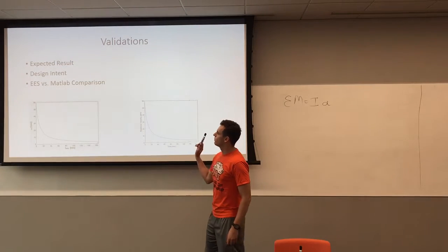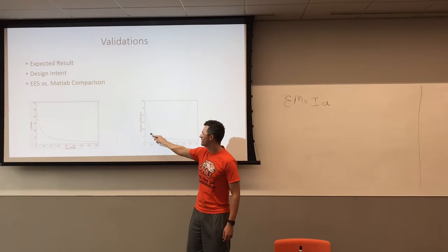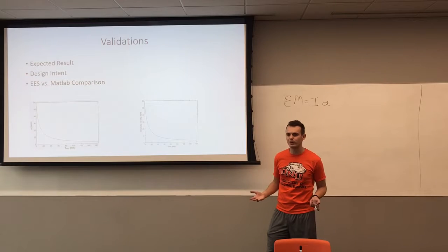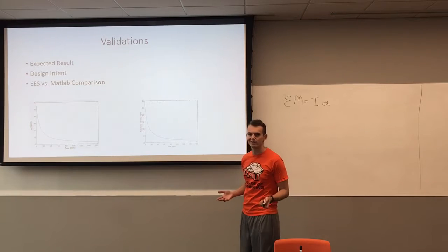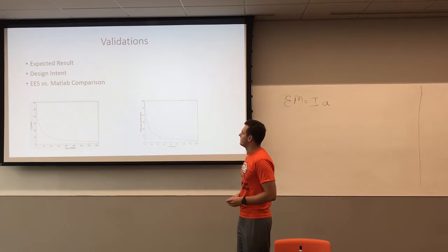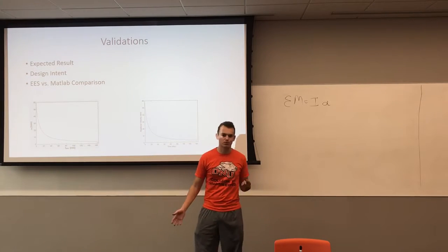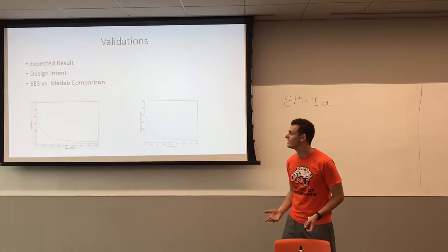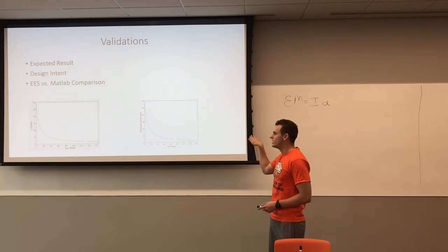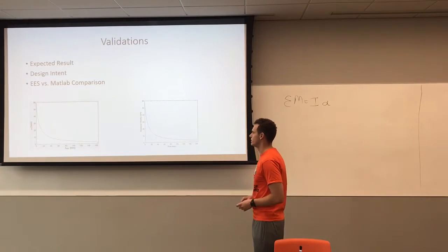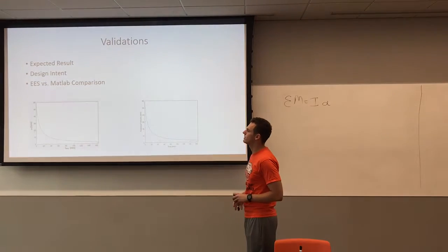Now, because it drops off so quickly here, and because 60 RPMs is not typically what a helicopter would operate at, it's more in the neighborhood of 300 RPM. Given that, you can assume that they would probably have approximately 2 to 3 minutes at least to land it, based on the general shape of the graph, if you were to extrapolate that out to the 300 RPM starting velocity.